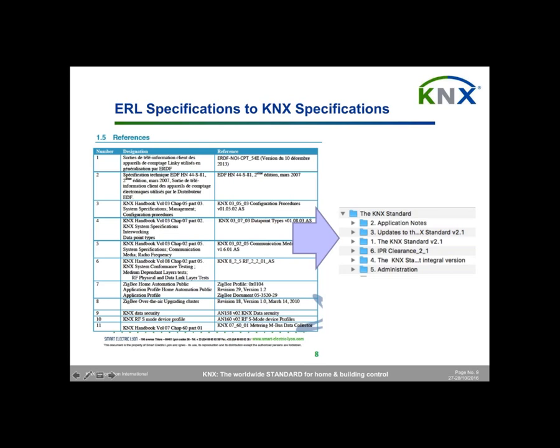It is basically a serial communication with two modes. One mode is the historic mode, which is the slowest mode at 1,200 baud, with some limited fields, information about the meter. It has a monophase case and a three-phase case.